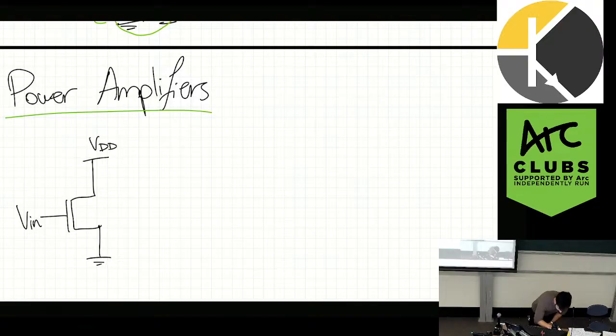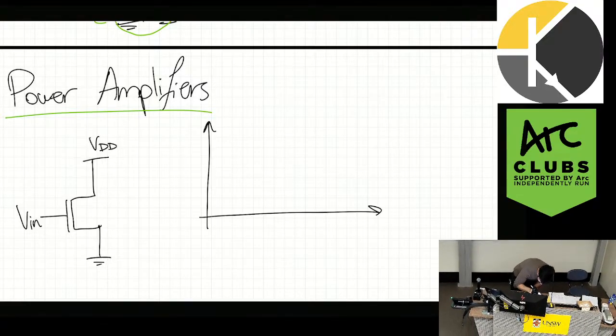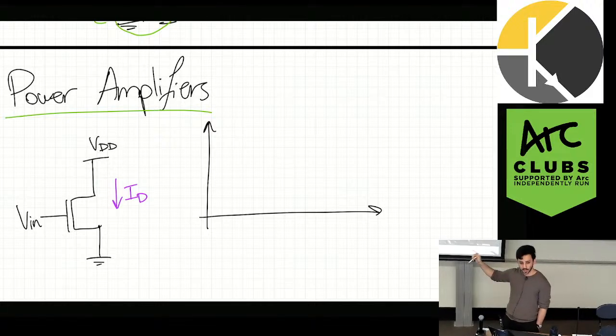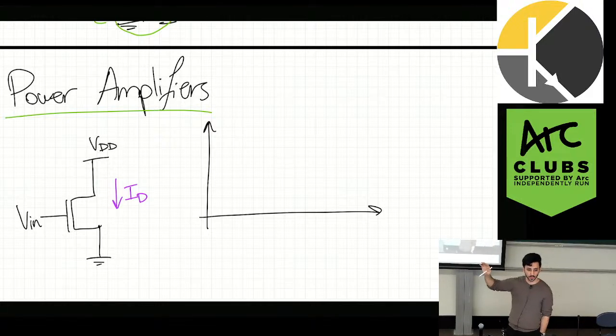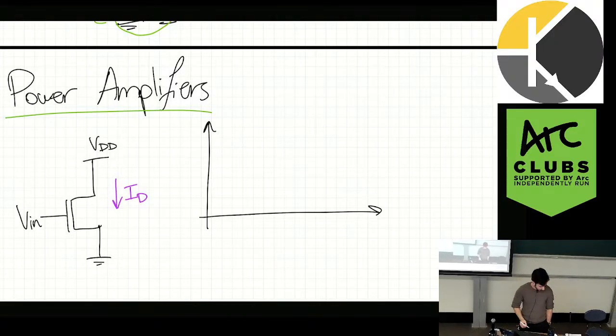So when we look at the first condition, what I want to look at is the drain current. So that's the current flowing through. So again, there's another condition which says that the V drain source must be greater than the V gate source. We're just assuming that's fine, right? That's not the important condition. That's not very hard to fully satisfy in power amplifiers. And it doesn't really explain the different stages, okay? The different stages are dependent on the first condition, right?